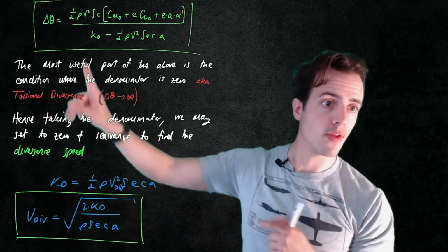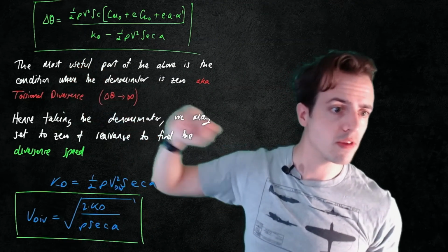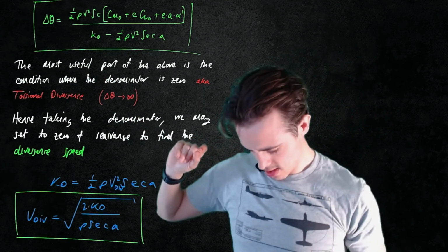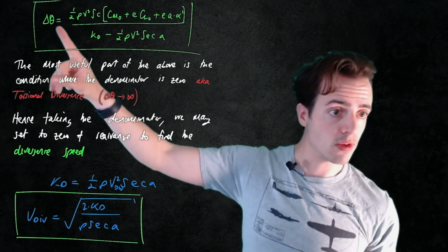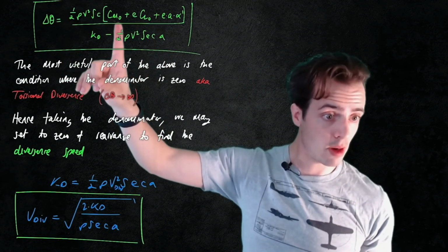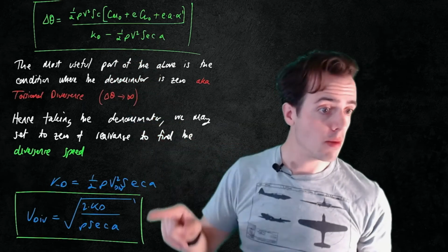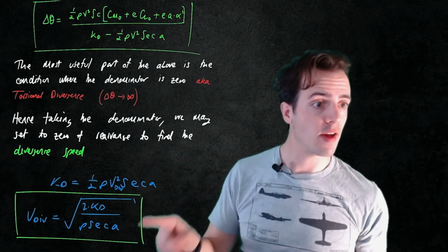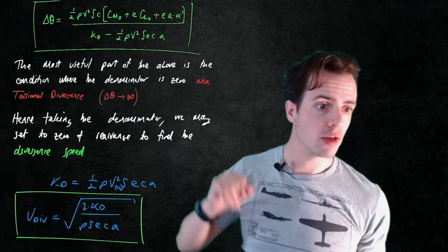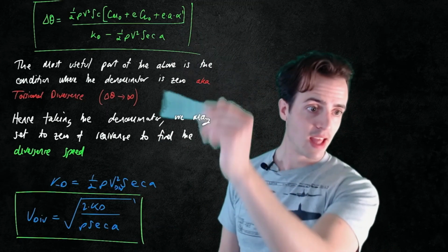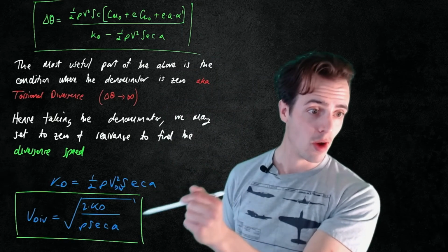We can see here that the torsional stiffness is a function of, let's just check I've got everything in here. Yeah, so we can see up here that delta theta is a function of the zero lift pitching moment coefficient and of the zero incidence lift, but they don't appear down here because they don't affect the denominator of this expression. We can also see up here that it's a function of the rigid angle of attack, but again, it doesn't occur in this equation down here.